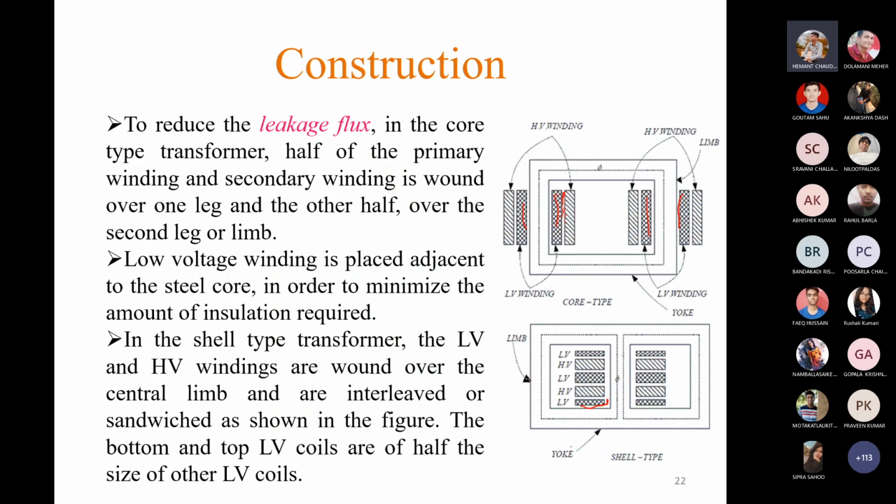There are different types of cooling methods. You might have seen in larger transformers there are some blade shaped arrangements, and beside those blades some fan is revolving. Those are forced cooling. If you can arrange those, then the shell type of transformer can be used, because here the windings are covered by the core, so you need extra cooling arrangement. But in case of core type, if the transformer rating is very high, then you will also require extra cooling arrangement. For a smaller transformer, you don't require any extra cooling; natural cooling will be sufficient. Okay, so there are so many constraints.